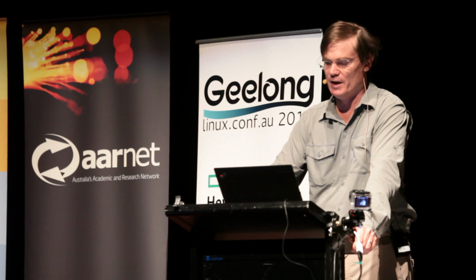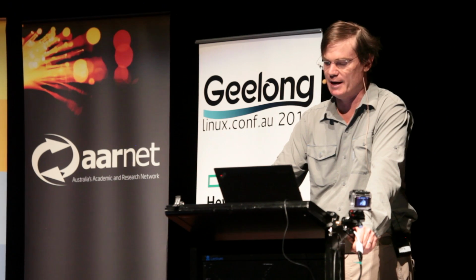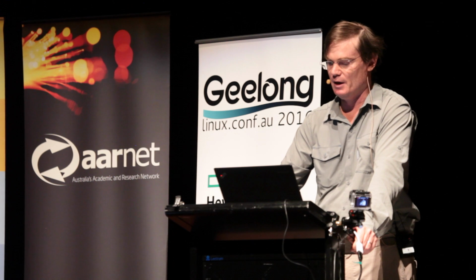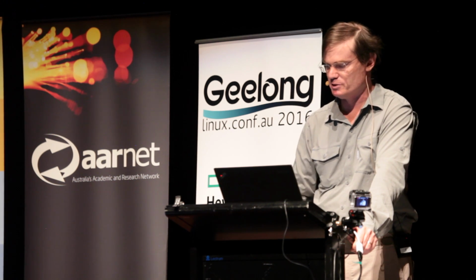And so we had a severe RF noise source at the 900 megahertz band, and that caused us to get a number of dropouts. It was still controllable the whole time, but we would like to get rid of that noise floor.